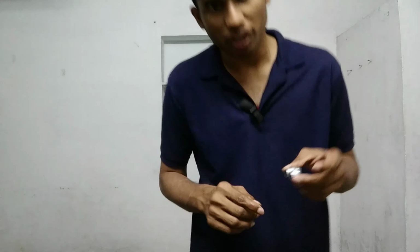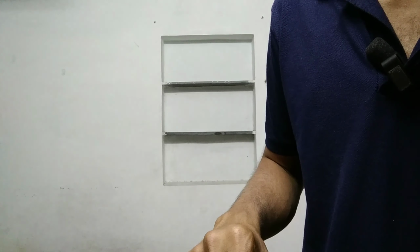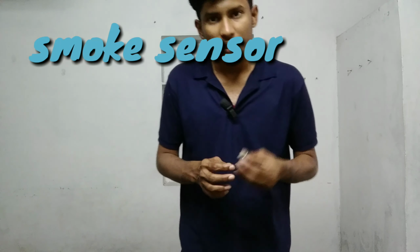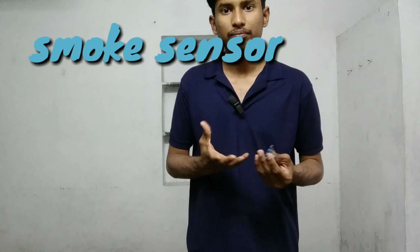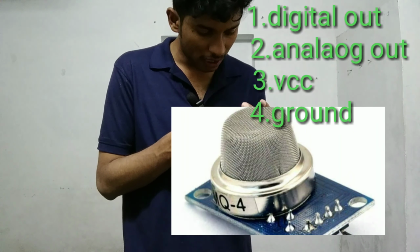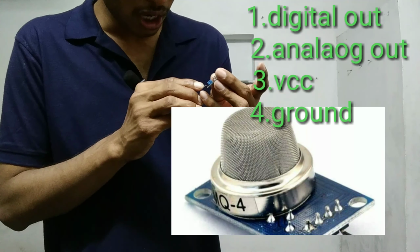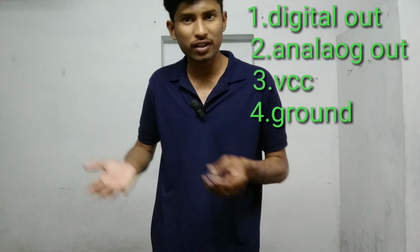And let's come to the next sensor. It is nothing but the smoke sensor. This smoke sensor will produce an output when smoke occurs, and it has 4 pins: digital out, analog out, ground, and VCC. The VCC is connected with the 5V pin of the Arduino board, and the ground is connected to the ground pin of the Arduino board.